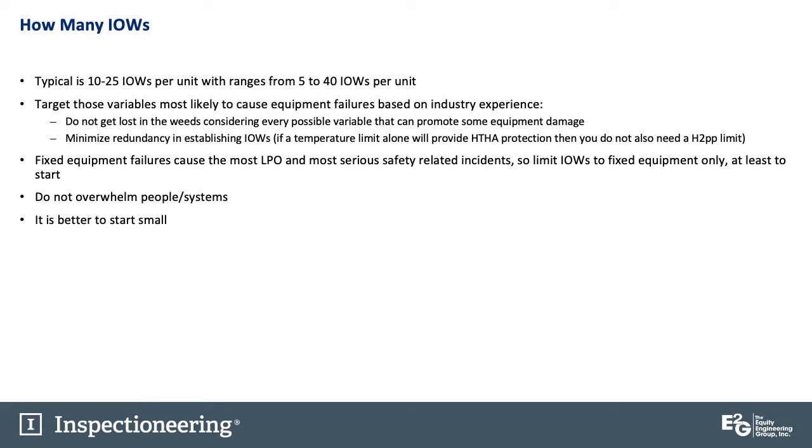I think refineries that have implemented some of these IOW programs, in some cases, put together IOWs for all their refinery units and then got their PI tags information into their notification systems. Then they hit the go button and the people who get notified on exceedances get overwhelmed with the data to start sometimes. So there's often some adjustments needed to the actual IOW ranges.